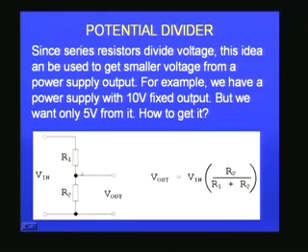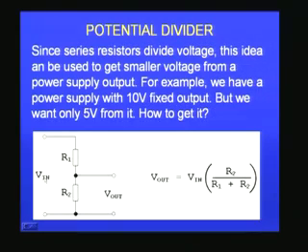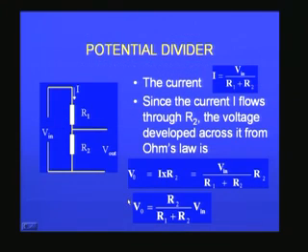10 ohms will make a large current continuously flow through the circuit, and therefore there will be a large current flowing through these two 10 ohm resistors. That means there is a power loss in terms of the power rating of the resistors R1 and R2. There will be some heat loss in these resistors which will be unnecessary, and therefore one has to have some via media in between. You should not use too large values, you should not use too small values, and therefore you will use reasonably small values, like maybe 1000 ohms is a reasonably good value that you can think of.